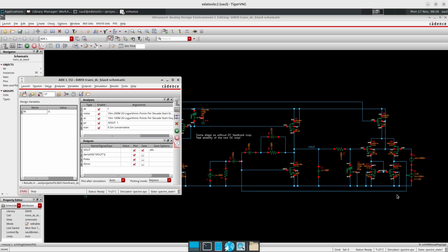And another thing is that I have added this pulse voltage here, so I want to test the transient response, if it has overshoot, if it oscillates. So I will be adding a 100 millivolt pulse to the 900 millivolts DC that I have, and check how the loop behaves, how much overshoot we have in the output. Okay, so we'll be running the simulation.